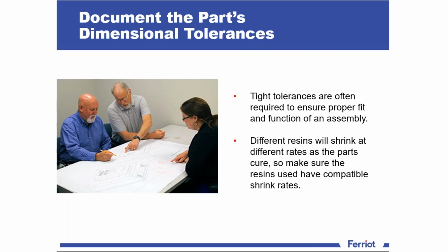Document any dimensional tolerances for the parts. Tight tolerances are often required to ensure proper fit and function of an assembly, and different resins will shrink at different rates as the parts cure.